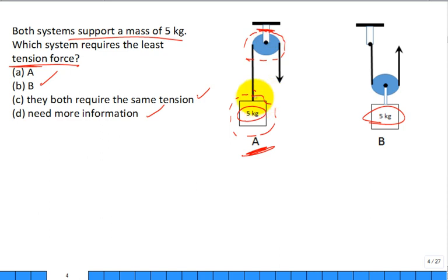So if you do a free body diagram of the weight, the mass, it has the weight going down. What is the tension in the cable pulling it up? It's equal to the weight. Guess what this tension that I'm going to have to pull down on is equal to, going around a frictionless pulley: the weight of the object. So if it's 5 kilogram force or 5 newtons or 5 pounds, then it's 5 pounds tension that I'm going to have to pull.